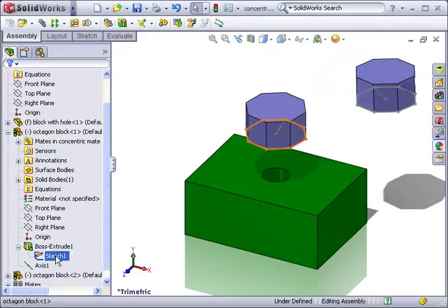When you're finished up, simply hide the sketch. One thing to keep in mind is because you're using the sketch geometry as the mate reference, mates created like this can break easily in certain situations. Now this might work fine in a lot of situations, but if you find that the mate keeps breaking this way, you can use the axis instead.